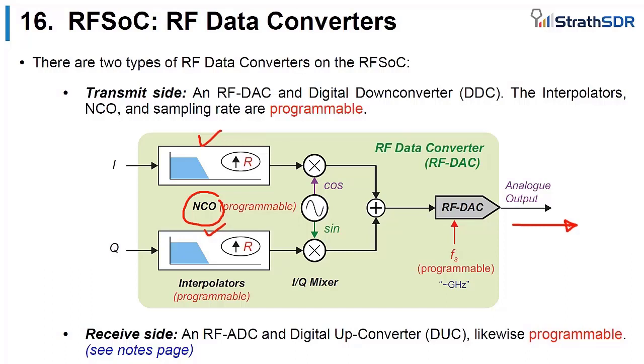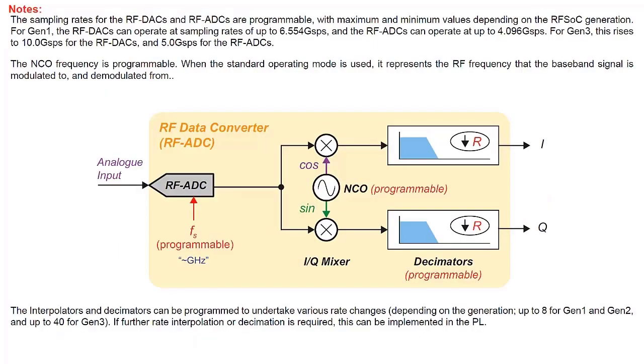And at the other side, we'll of course have the direct digital down converter, the DDC. We receive a signal and then mix it down to baseband, and I'll tell you a bit more about that later. There are a number of filtering stages, and usually we have IQ data and we send that off for processing.